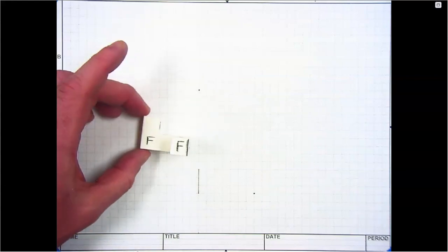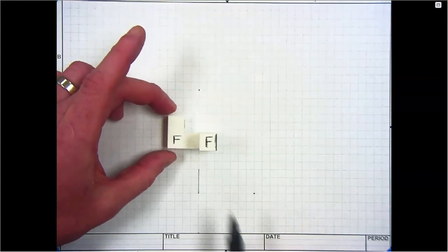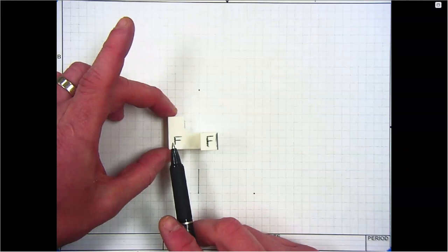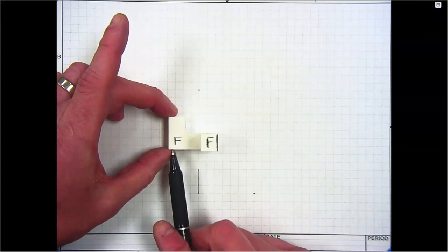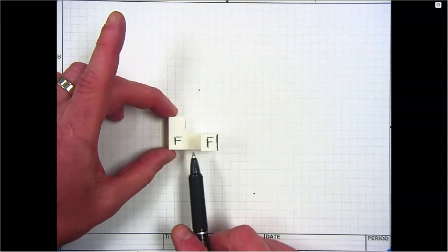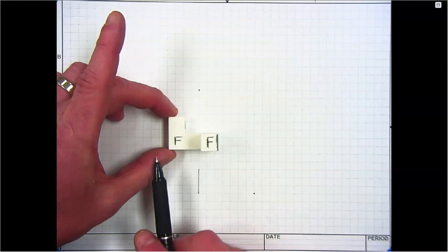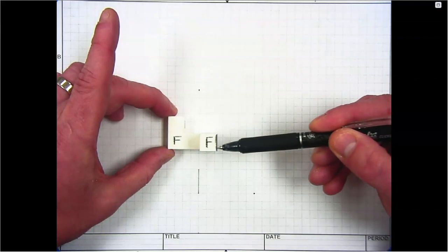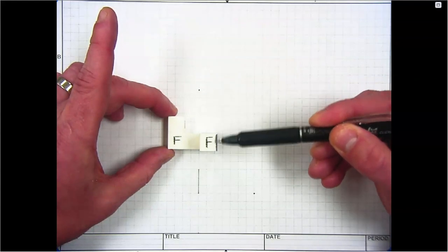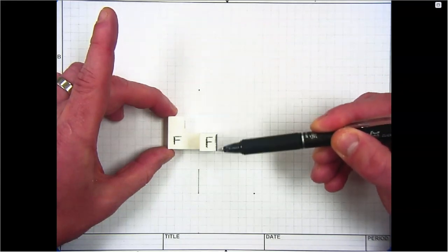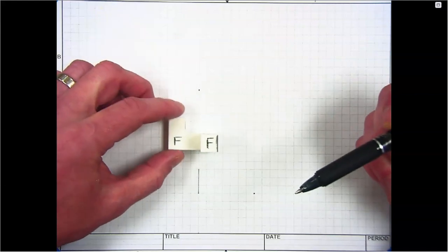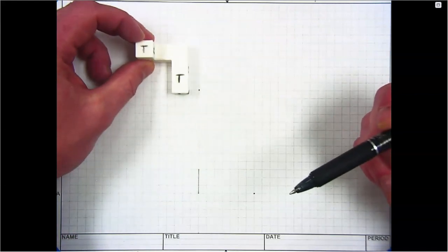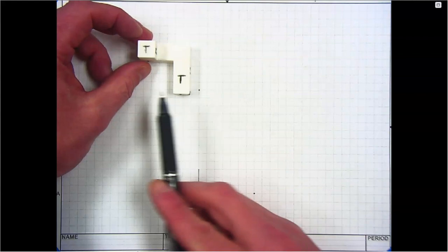So a few reminders on drawing parts. The front view holds two dimensions. The first dimension that is shown in the front view is width. It runs from left to right across the object. And the second dimension is height. It runs from bottom to top across the object. The two dimensions that we'll be drawing in the front view.